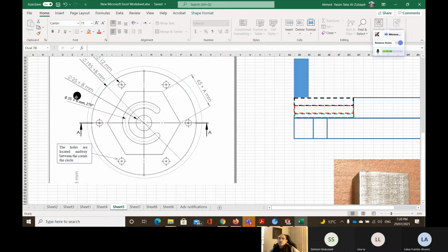You don't have to show me all the code for cutting the material to make it a circular shape. You only need to show me the code to remove 1 millimeter diameter from the side. And this will be very simple because we come to here, we go to the minimum depth, which is Z. For example, if the height of the work part is 20, you go to Z minus 20, then you do G02 to here, then G02 to here, and then G00 to Z equal to 5. Then you go to whatever the point is, the home of the machine.